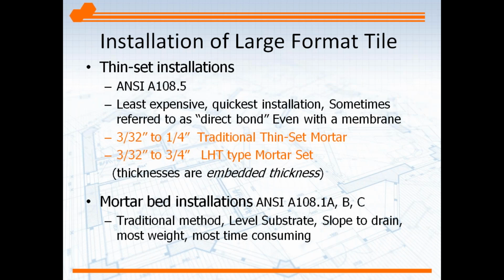The good news is, if you look at the LHT mortar on the bottom line of orange, you'll see that it goes in as thin as a traditional thin set. So you really only need one mortar on the job site. The LHT mortar will do it all. You don't need a traditional thin set and an LHT on the job. If you're putting in 4x4, 8x8, or a mosaic, you can use the LHT mortar for both installations. Also, mortar bed installations. You can use a traditional mud bed and a wet set mud bed if you want as well to install a large format tile, which is in the ANSI 108.1 A, B, and C, depending on your situation.